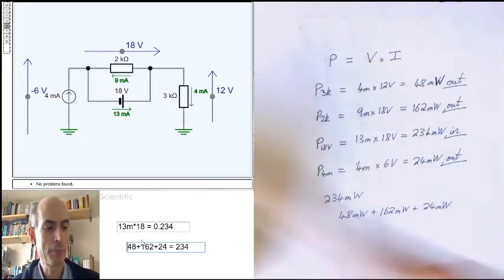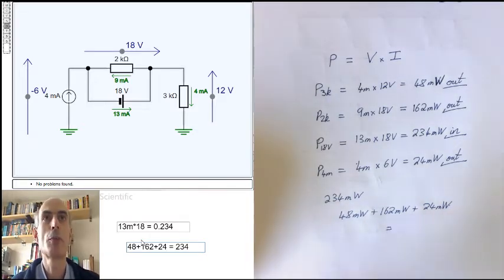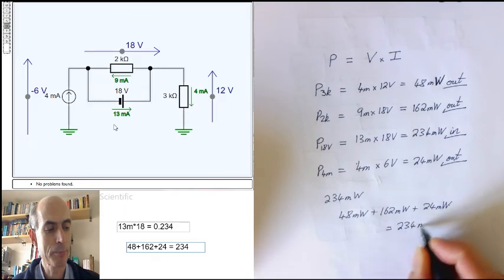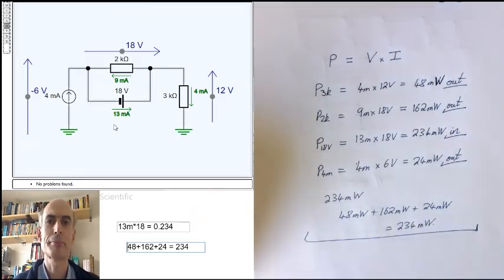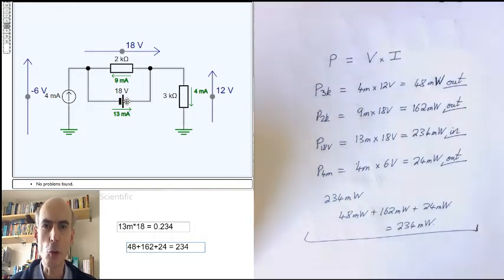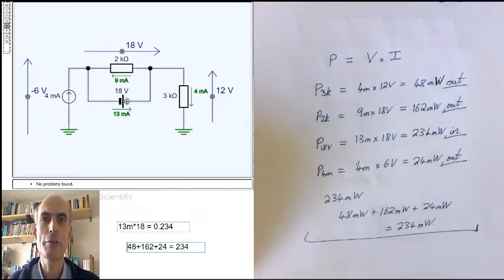Yes, it is. That's good. That means that we've got our mathematics correct and energy is being conserved as we expect. The only slightly unusual thing here is just to remember that current sources and voltage sources don't always supply power to circuits. Sometimes they take power out of the circuits if the current flowing through them is going from a higher potential to a lower potential.